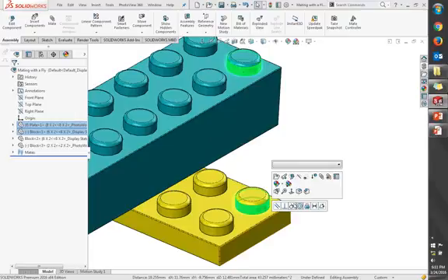But ultimately, if you use SOLIDWORKS for a little bit, especially when you're mating stuff together, you realize that concentricities are automatic. You realize that coincidences are automatic. You realize that tangencies are automatic. Well, that's all the ones that are being shown right here as well. So it's like, hey, look at that. Now, I can see here that this button is actually pre-selected for me, and I could click it. So it means I don't have to try to figure out what the hieroglyphic is. I could go, oh, that one's the one that's kind of shaded, so I'll click it.